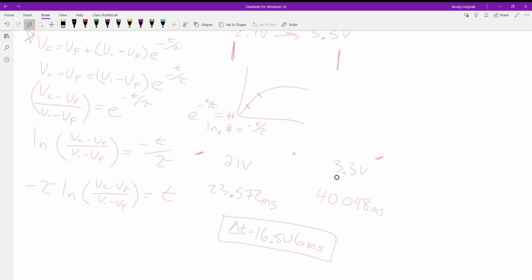There could be times that you want to know how long does it take to go from 0.1 volt till it gets to 7 volt? Whatever your application is, that's kind of the idea. We can have this range and we can decide what we want it to wait for. And then the voltage finally, the 3.3, or was it the 10? It's the 10. It's the final voltage the capacitor is trying to get to.